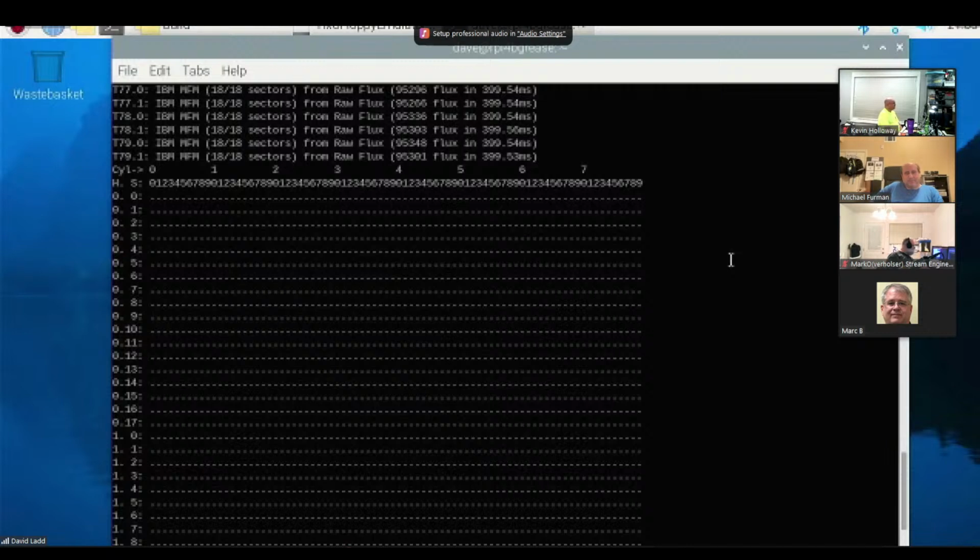But otherwise, the Greaseweazle's still a great option. And if you want to try building your own, the information is on the Greaseweazle's GitHub page under the wiki about the F1. So you can build your own, though that version only supports one drive connected to it. And if you want a pre-built version, the wiki has links to places that you can buy the F7, the version 4, and I think the version 4.1, which is well worth it if you still deal with floppy disks.